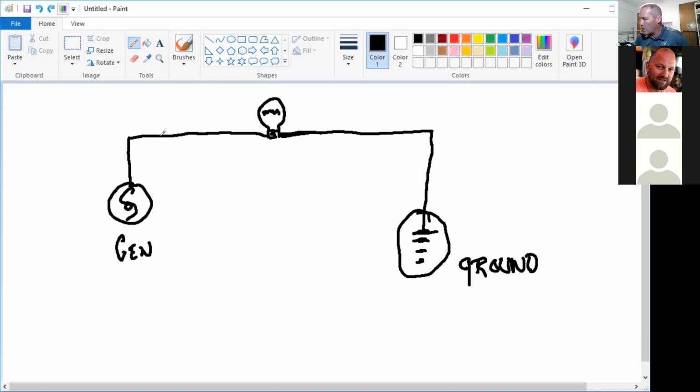My first switch right here, and I'll put the open symbol, that's an O. Where now is voltage present? Do I have voltage present here? Yes. And here, prior to the switch? Yes. Do I have voltage presence here? No. No, I do not have voltage presence through the rest of the entire circuit after the open switch.